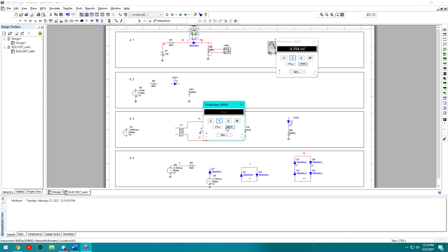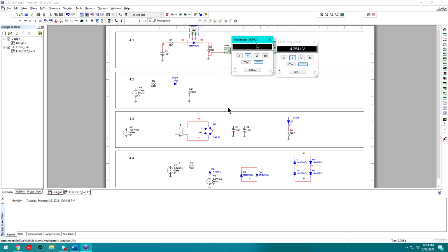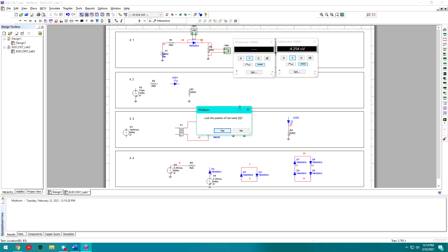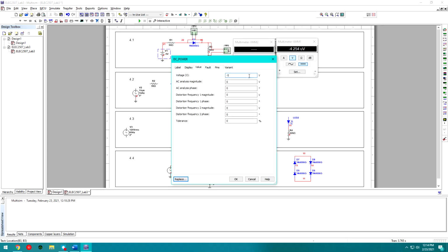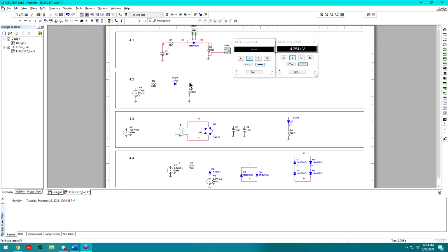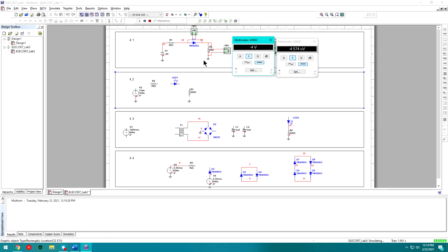And we'll look at the voltage drop across the diode as well. And we can see that the voltage across the diode is also 0 at this point. So we'll put that one first. And then we'll keep increasing this step of the DC supply in steps of 1 volt until we end up at positive 5 volts. So from here, we'll say we have negative 4 volts across the diode at negative 4 volts at the input, and we still have 0 volts across the load.